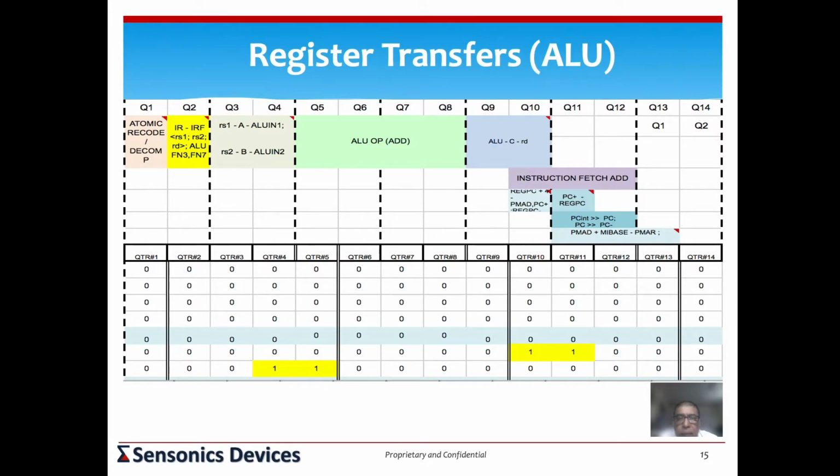That should happen if you're assuming, which we are, that the instruction fetch takes as much or slightly less than what the multiplier takes. The multiplier takes, we are setting 4 quarters as 1 unit, but the instruction fetch could be 3 quarters for the fetch. So as soon as the address is set, we say that this instruction's flowchart is over.